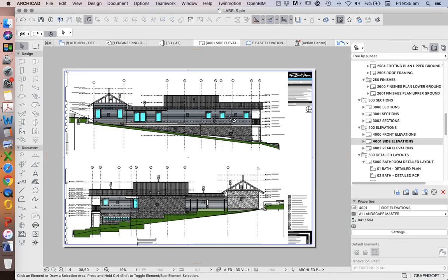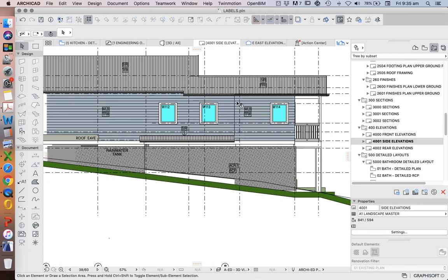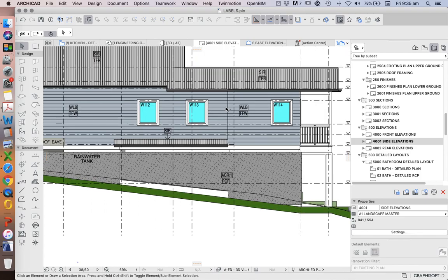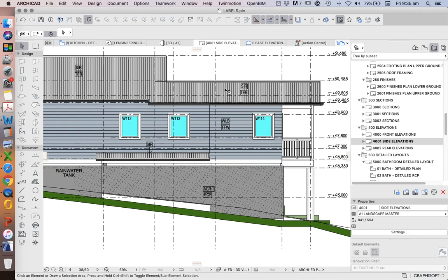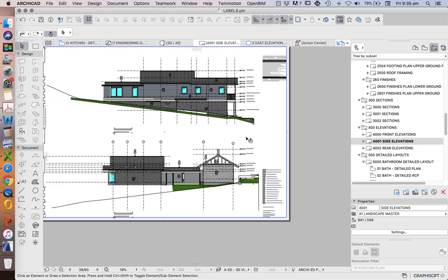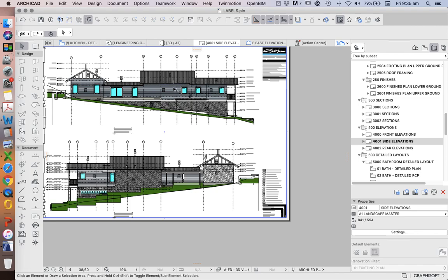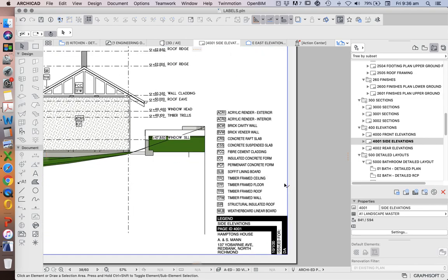When we're trying to describe surfaces, finishes on building materials of a building, any type, in this case it's a house, what do we do? Do we use a full annotation or a label acronym, and how is that created? How is that referenced? In this case, what I've done previously is I'm using text. It's quite simple, it looks quite clean, and then I have a legend which helps to describe a little bit about what that is, and then of course that needs to be referenced to a material schedule to give more information about what that is.